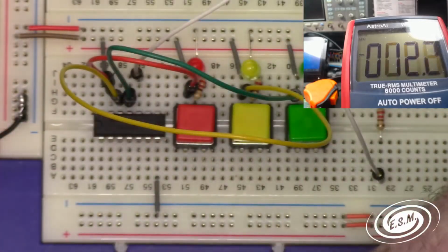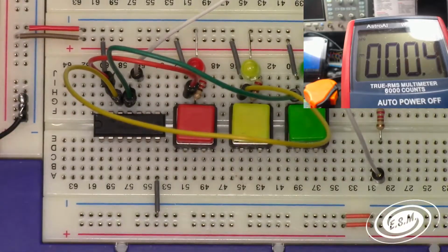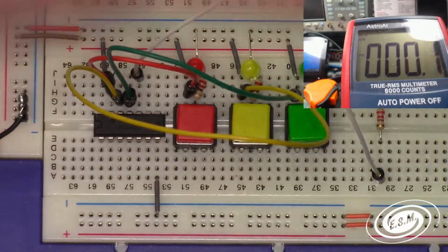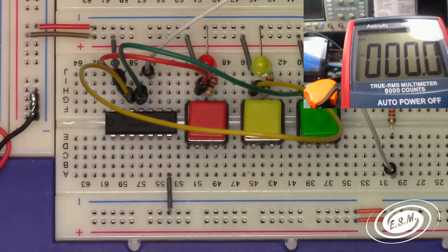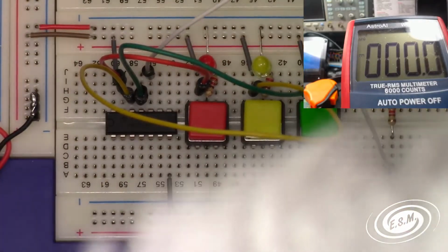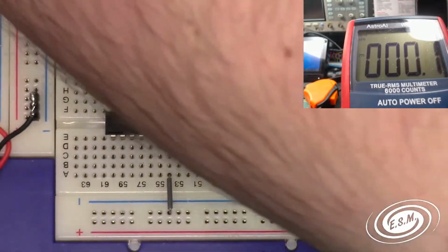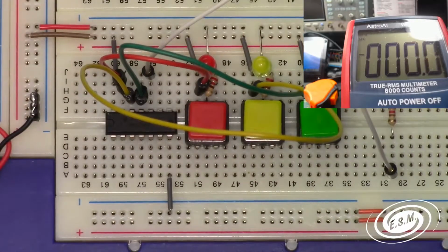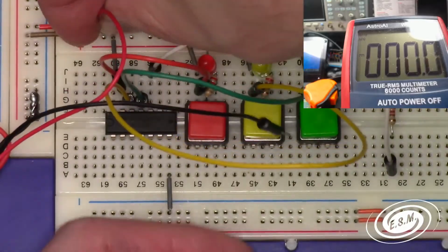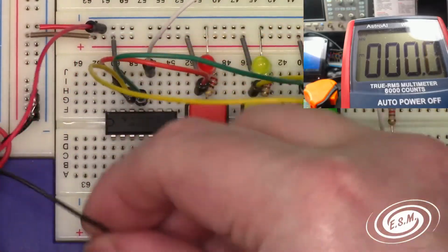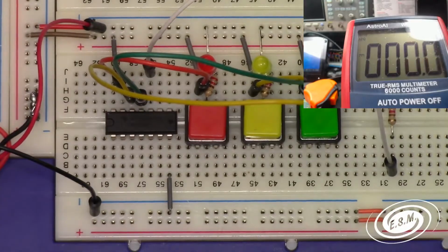I am going to do this. I'm going to turn my power supply off, pull these banana jacks, and hook up a different way of doing this. Let's see if that makes a difference. This is all about electronics, is troubleshooting. So take this. There, I'm going to plug my 5 volts here and my ground there. Turn on my power supply.